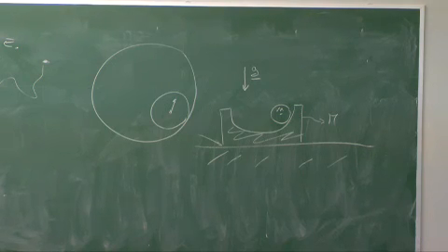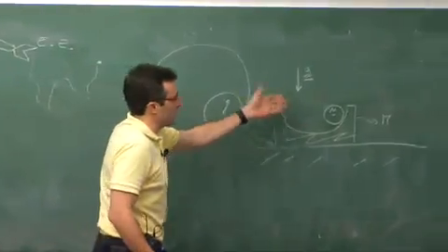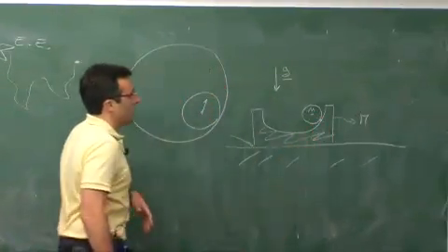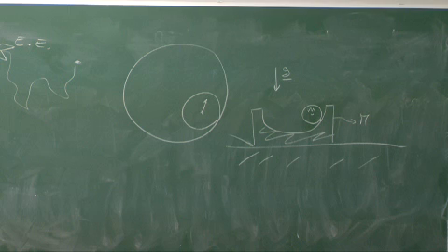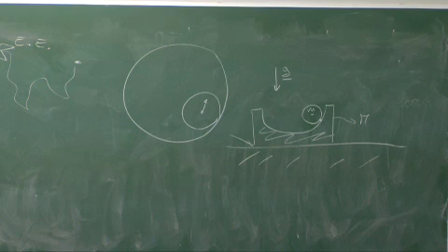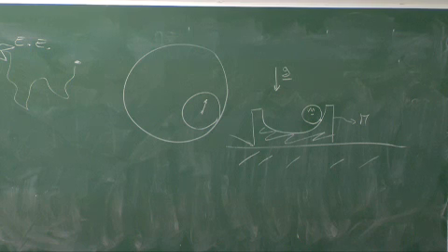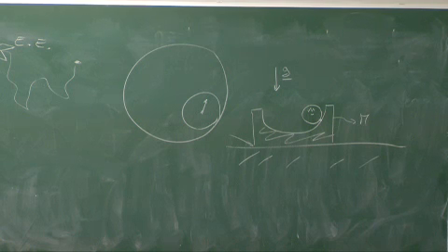Because there are two rigid bodies, and so you need, of course, at least two, that are exchanging forces and actions here, and they're moving together. This is just a more complicated one. So when you get to more complicated problems, you can still use the Newtonian approach and Lagrange's approach, but you may need tricks like this one, moving yourself to the center of mass so that you can write something you can actually manipulate and solve. And after that point, yes, you can have Kane's method, you can have a bunch of methods, but it really becomes a computational issue. You need to have good symbolic toolboxes to find your equations of motion.